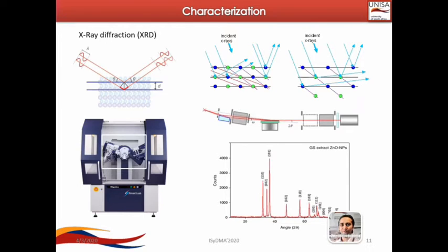About characterization techniques, it depends on the properties that we are looking to study. For example, here for the XRD, it is mainly used to study the structure of the material. And the XRD also can furnish different information. This includes the phases which are in our materials. The XRR is giving us an idea about the thickness of the materials, while SAXS mode can give us an idea about the size of our materials.